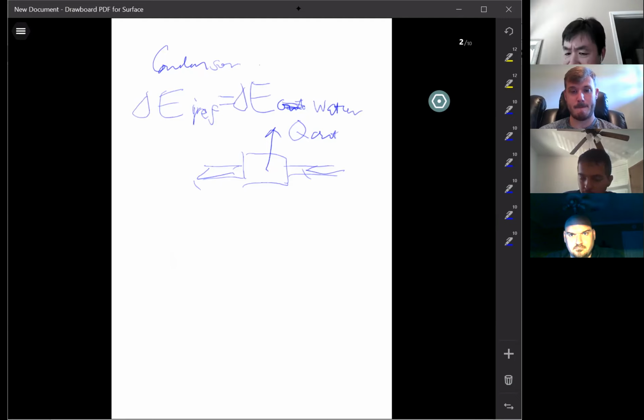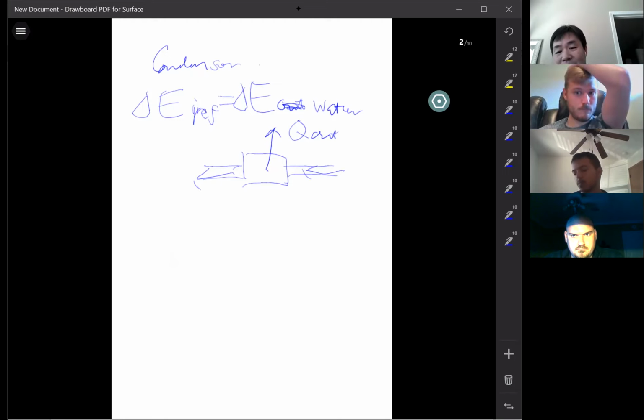That makes sense? So we're going to utilize this equation to calculate the mass flow rate of the refrigerant. In this entire unit, there's no measurement for the mass flow rate of the refrigerant. You don't need to. In any equipment, probably in your refrigeration system, you probably don't need a sensor to measure mass flow. Mass flow is difficult to measure anyway. You've got phase change and that kind of stuff happening in there. So they usually don't, but you should be able to calculate the mass flow rate easily. Use this balance.